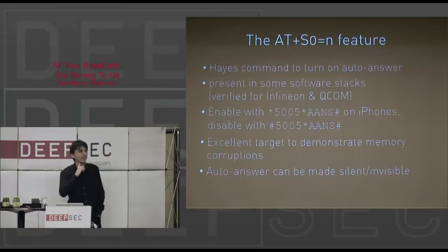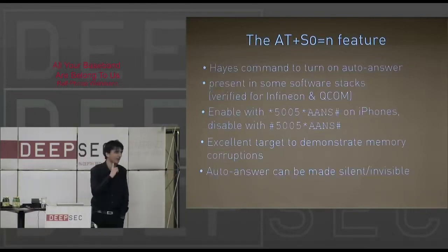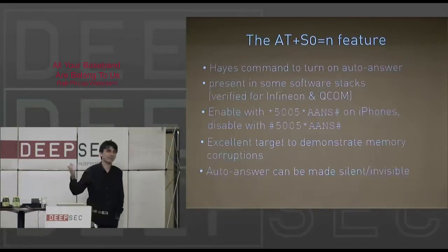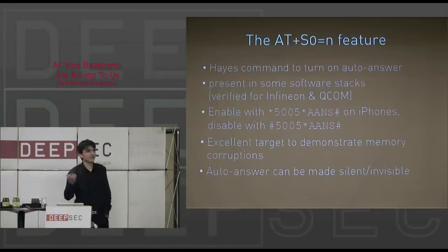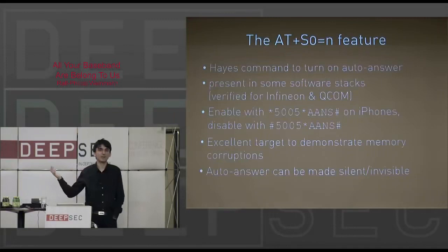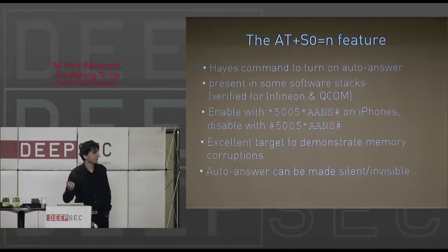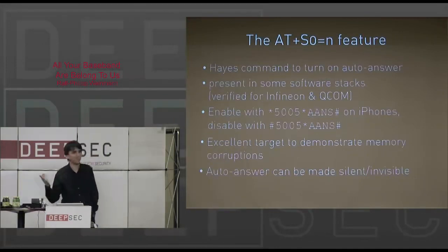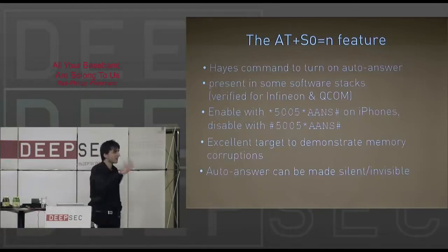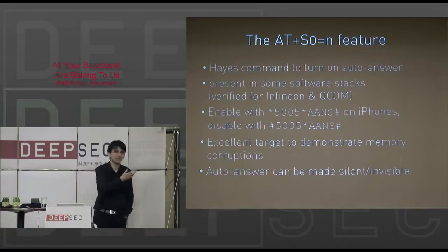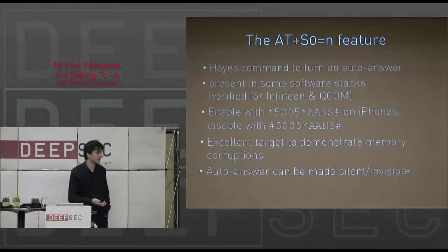I was surprised when I found this. I've seen this in the days when I used a modem. There used to be this Hayes command set for modems, and there's a thing, ATS0=number of rings, for turning on auto answer. This is present in some stacks, notably in Infineon and Qualcomm. You can enable and disable this on iPhones using this combination, which is not documented.